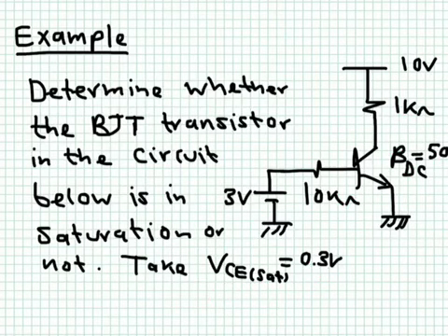Okay, so what we're going to be assuming now is that the voltage drop between the collector and the emitter is 0.3. If you have this 0.3, then I can determine the collector current, and the collector current is simply flowing this way. This is I collector here. So we can say that I collector is simply equal to 10 minus VCE sat divided by 1K. This will give me I collector at saturation. We can determine from that IB at saturation, which is I collector at saturation divided by beta, which is simply a threshold. Can we find the exact IB? Yes, of course we can find the exact IB if this is the base current. So we know that in saturation the base emitter junction is forward biased, so this is 0.7. So the base current in this case is equal to 3 minus 0.7 divided by 10K. I can determine the base current. I will compare my base current against the threshold. If it is higher than the threshold, then I am indeed in the saturation region. If it's lower than the threshold, then I'm still in the forward active region.